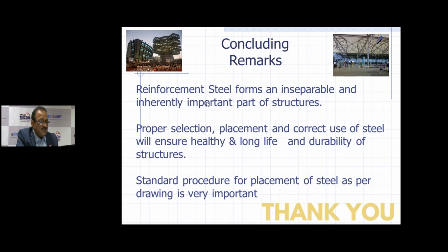So there is an indirect benefit of Portland pozzolana cement in preventing corrosion. There is no direct correlation, but yes, some cement companies I know, I will not name them here, call their cement corrosion resisting cement, but that is actually nothing but Portland pozzolana cement.